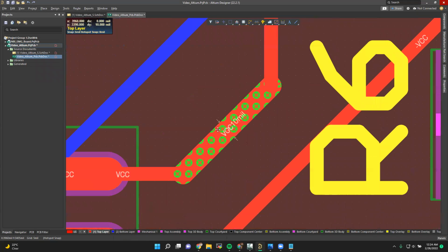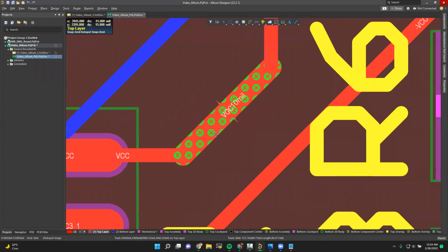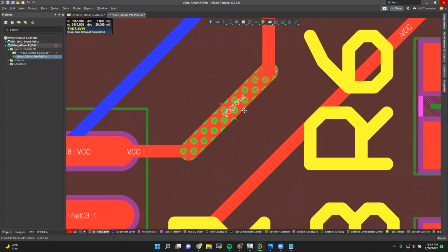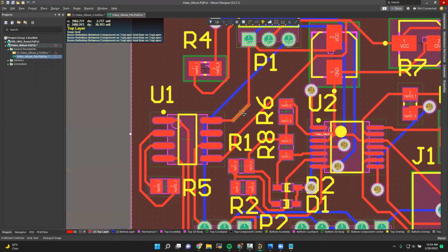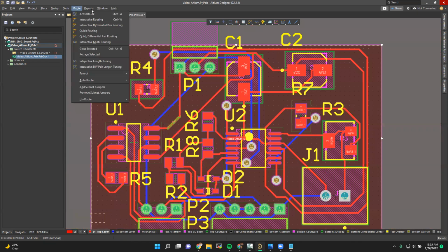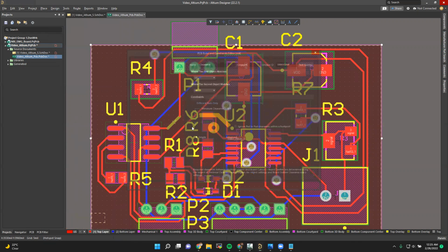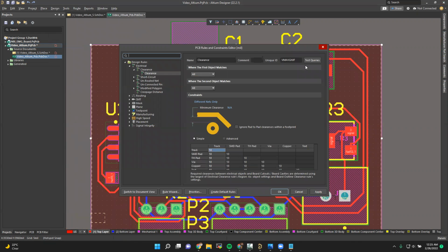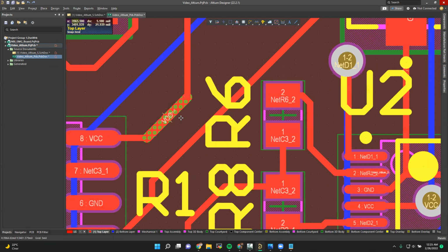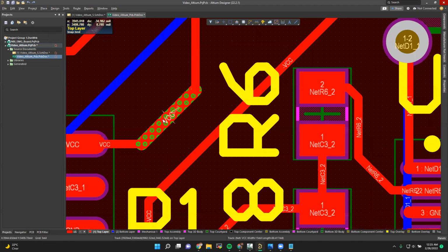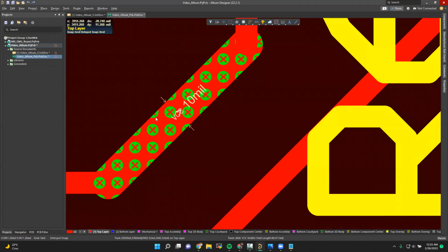This is telling me that Altium found an error in the design rules. I don't know if you remember, the last time I showed you in here the design rules for your project. For this specific project, I told Altium that I was not going to allow any traces bigger than 10 mil.